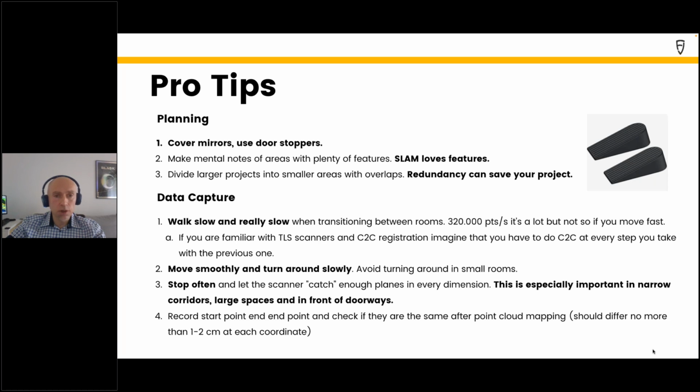You would waste more of your time repeating scans than on a slow pace. Stop often and let the scanner catch enough planes in every dimension. This counts especially, again, in narrow corridors, large spaces, and in front of doorways.